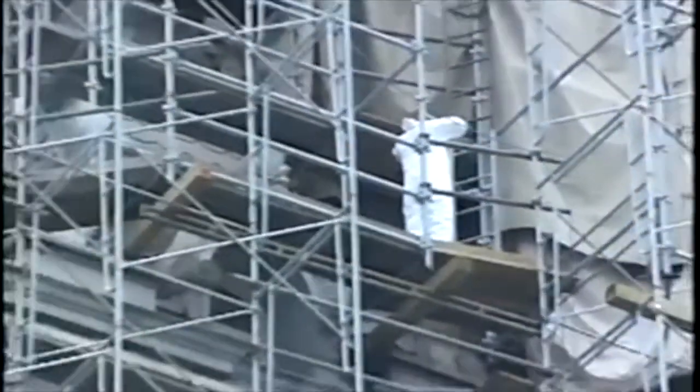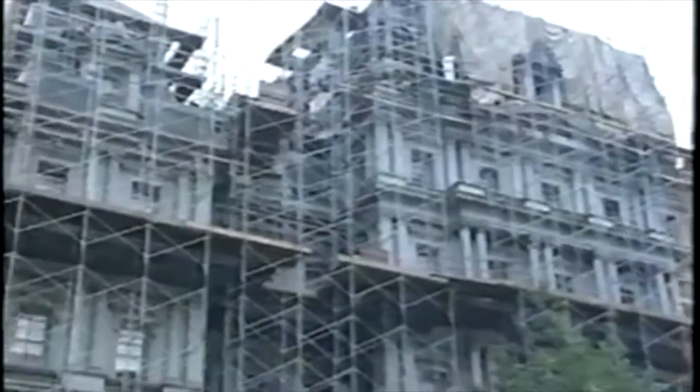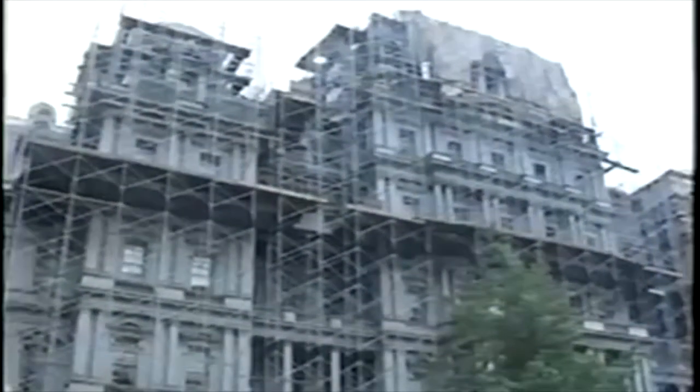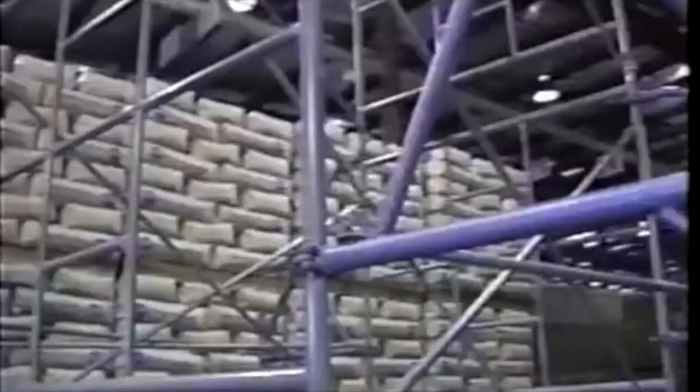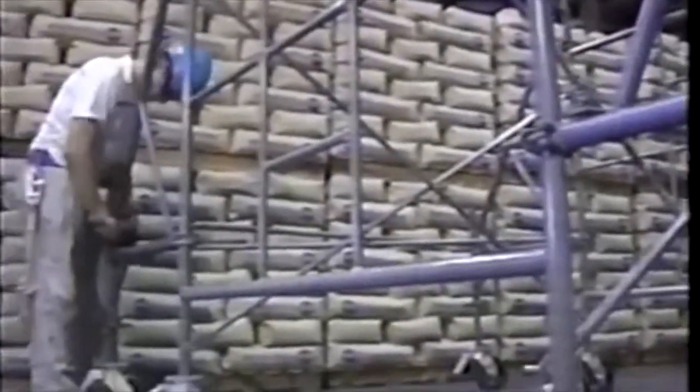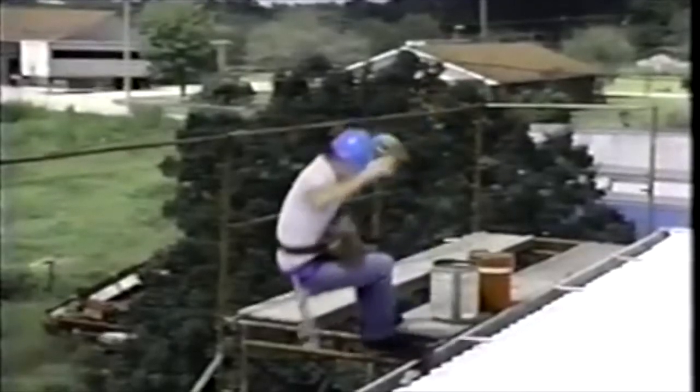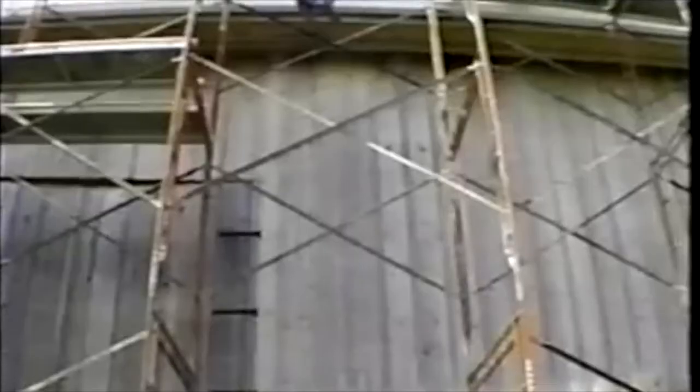In review, accident data tell us that the most important item to inspect on any scaffold is the fall protection system and the stability of the structure. Falls are by far the leading cause of scaffold fatalities. Since scaffolds are elevated work platforms, all components contribute to fall prevention.